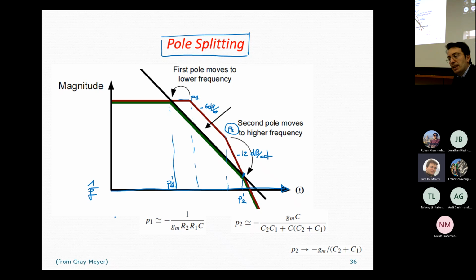Okay, because we have two closely spaced poles, so minus 180 degree phase loss achieved in a very short frequency range. The blue case can be more stable thanks to the separation. The red case is, let's say, the more stable combination, because the phase shift induced by the second pole is occurring at very high frequencies.